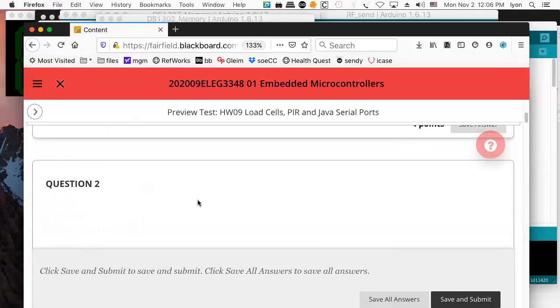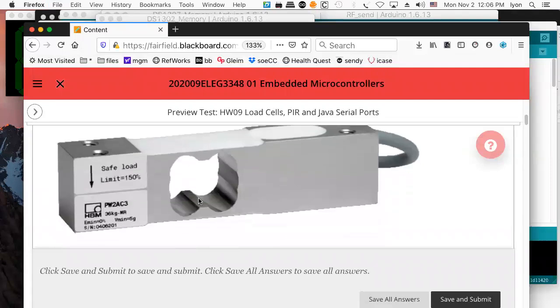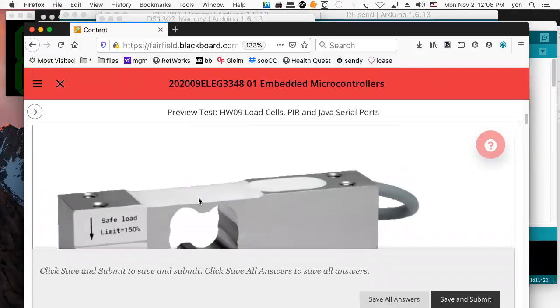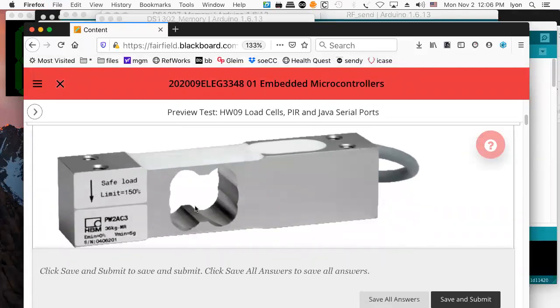That sounds good. Oh, here's a picture of a load cell. And you can see they've drilled it out to make it so that when its deflection is made at the end and it's fixed at the other end, presumably as long as you stay within the 36 kilogram rating for the cell, it doesn't have plastic deformation.